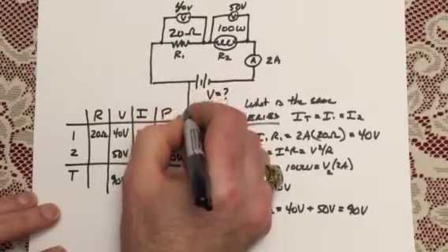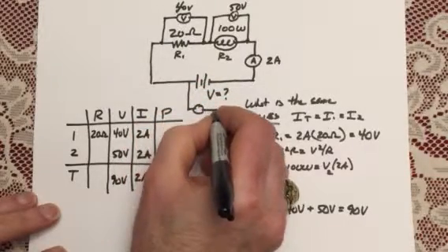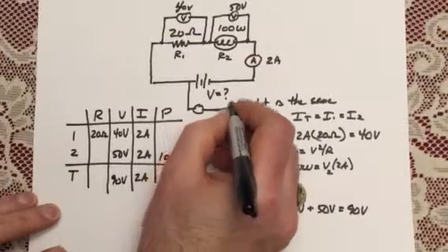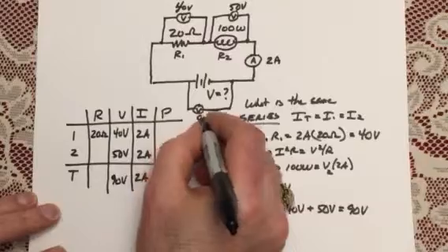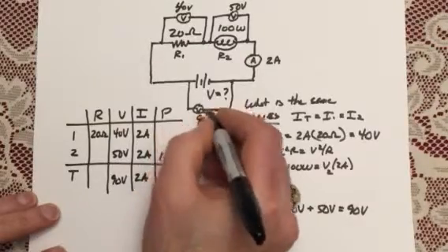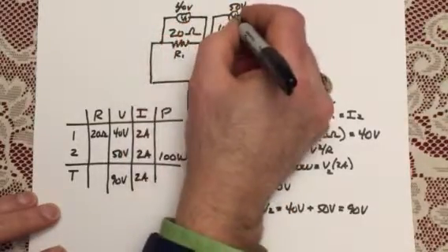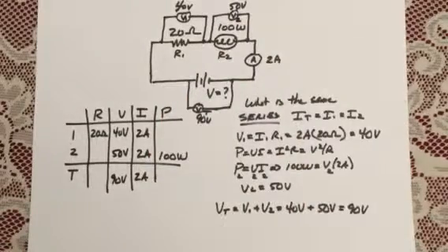And if I put a voltmeter across my battery, I'm going to go a little further out here so I don't go through my markings there. V, and that gives me 90 volts, and that's V total. This is V1, this is V2, and we're all set.